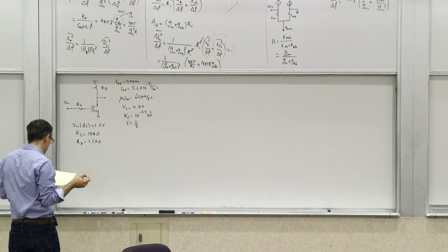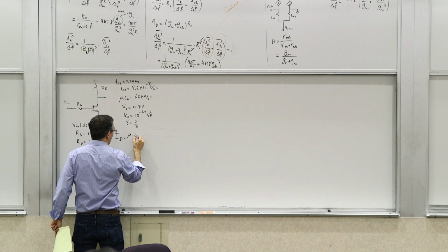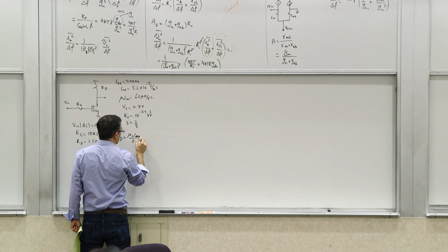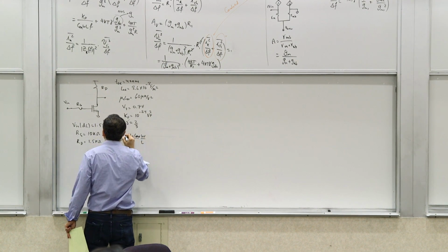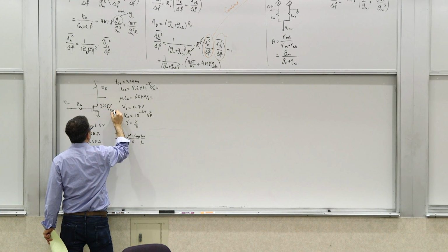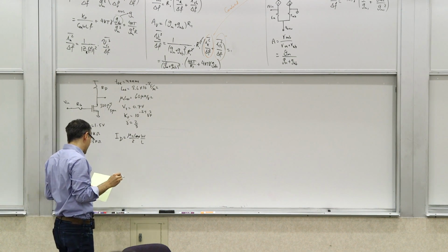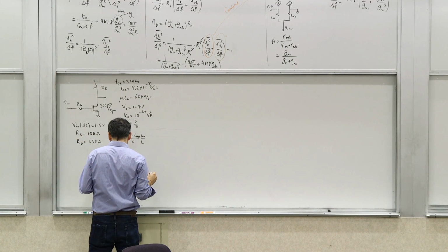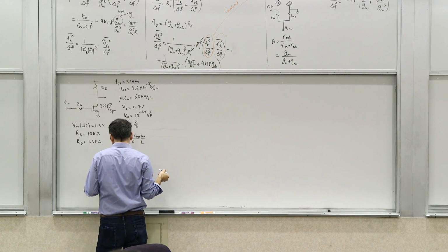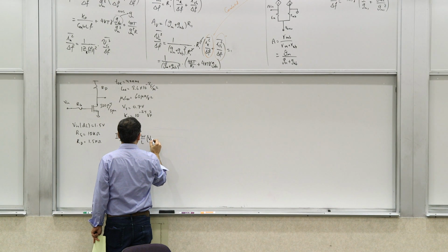So if you take these parameters, you can calculate, first of all, what the DC current is. ID is, let's say it's non-velocity saturated, so mu n Cox over 2, W over L. Oh, I have to say what W over L is. Let's say 300 micrometers over 3 micrometers. So it's a pretty long channel. It's not going to be velocity saturated for the 5-volt supply.